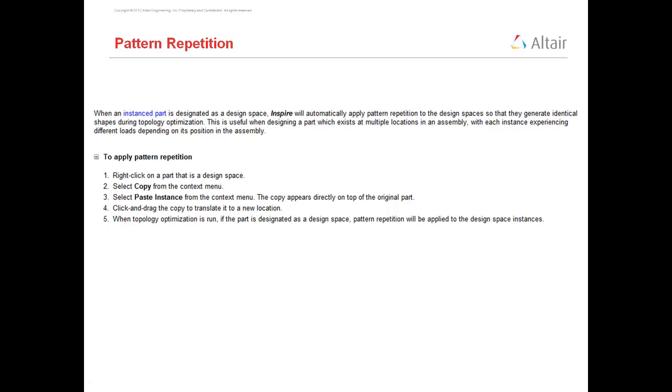When an instance part is designated as design space, Inspire will automatically apply pattern repetition to the design space so that they generate identical shapes during topology optimization. This is useful when designing a part which exists at multiple locations in an assembly, with each instance experiencing different loads depending on its position in the assembly. So now I'll show you how to create instance parts.